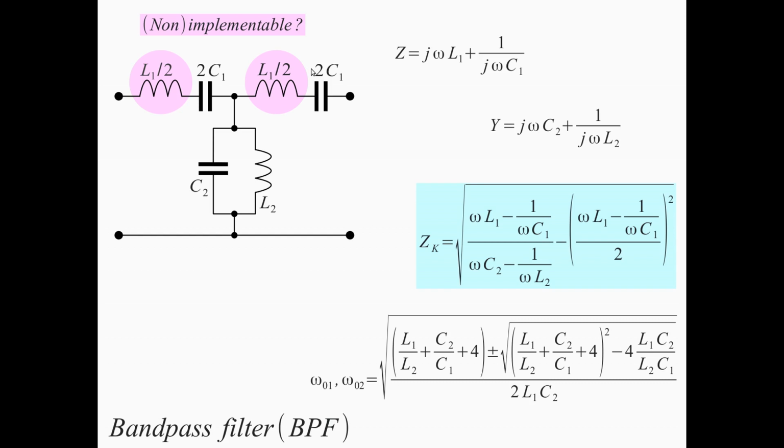First, it makes sense to make a better choice of the frequencies, because we actually have two frequencies. We have the resonant frequency of this circuit here, and the resonant frequency of this circuit here. Not to have arbitrary choices, but to choose these two resonant frequencies to be identical. So that is the first choice we may have to make.